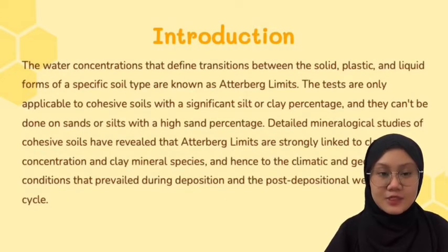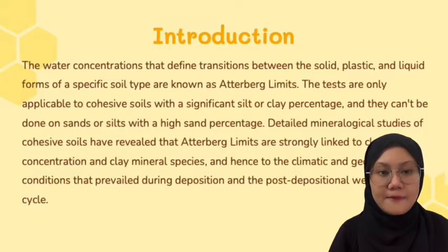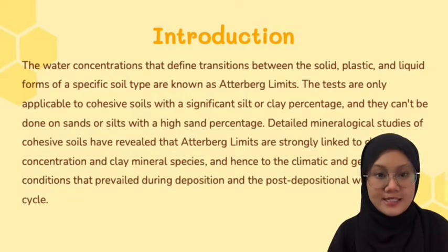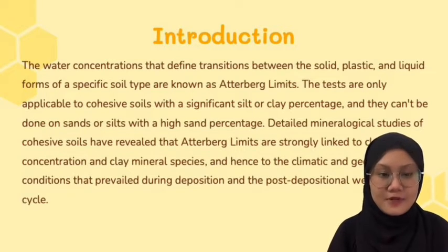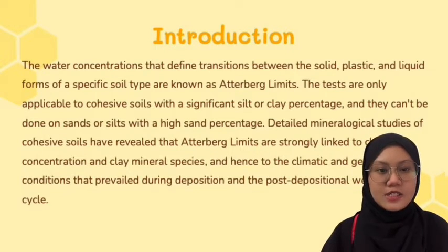Okay, now I'm going to start this presentation by introducing what the Atterberg limits are. The water concentrations that define transitions between the solid, plastic and liquid forms of a specific soil type are known as Atterberg limits. The tests are only applicable to cohesive soil with a significant silt or clay percentage, and they can't be done on sands or silts with a high sand percentage. Detailed mineralogical studies of cohesive soil have revealed that Atterberg limits are strongly linked to clay concentrations and clay mineral species, and hence to the climatic and geologic conditions that prevail during deposition and the post-depositional weathering cycle.